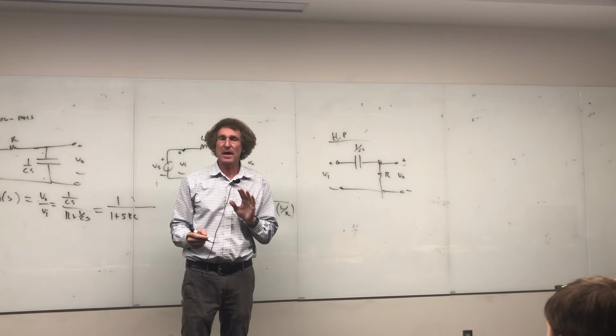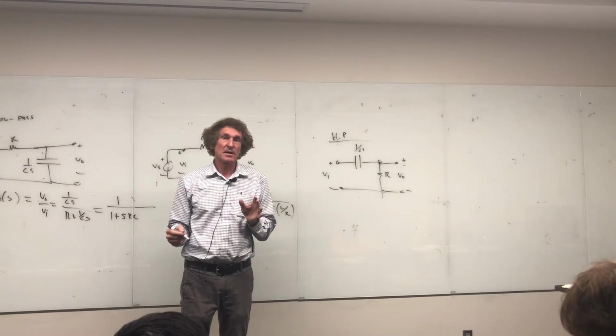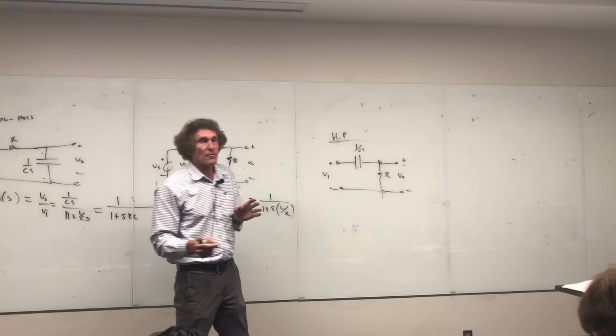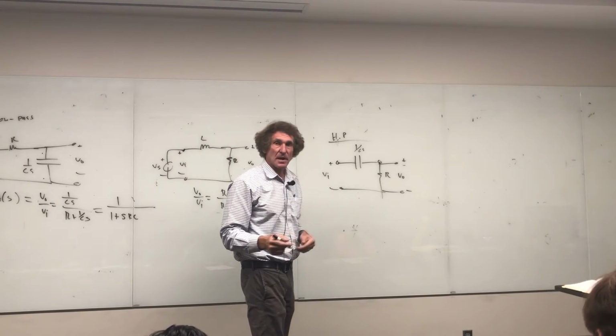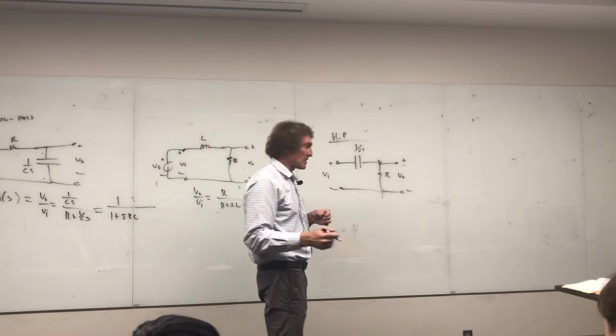Without going into detail, you've had filters. These are cheap and they work. That's the reason I'm talking about them. They're dirt cheap, and they work for most things where you don't need a lot of roll-off. These are all 20 dB per decade roll-off, nothing higher than that.